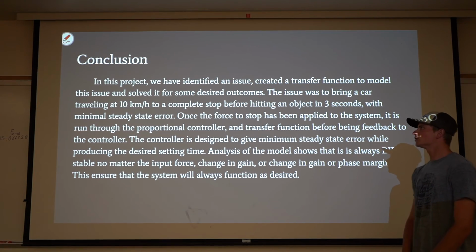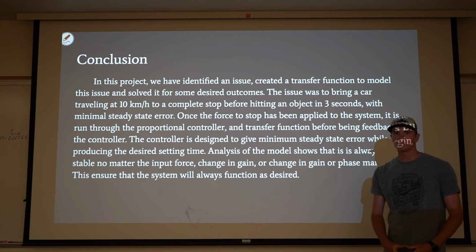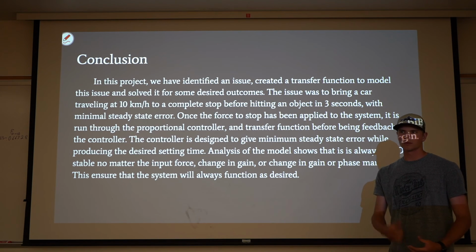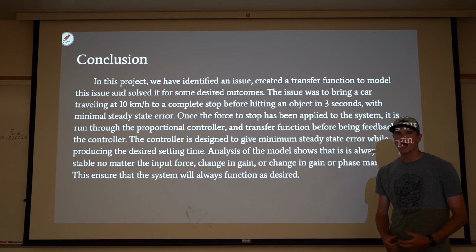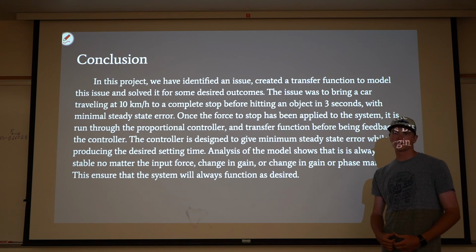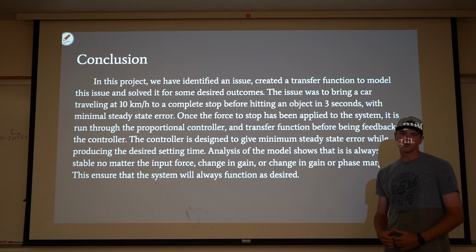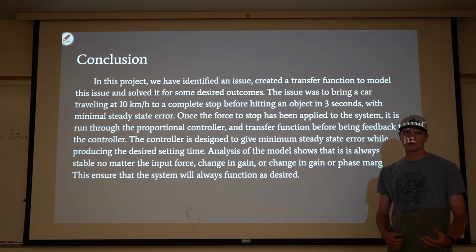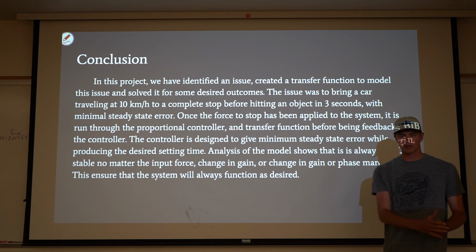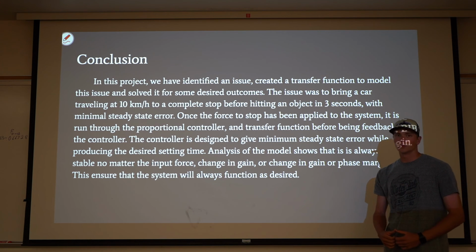So in conclusion, in this project we identified our issue of an automated car coming to a complete stop. We couldn't have a large steady state error, because then there would be the possibility of the car running into a pedestrian or something else. We had to create a decent rise time and settling time, more importantly settling time, because you didn't want the car to take 10 minutes to stop, and you wanted to eliminate the overshoot.